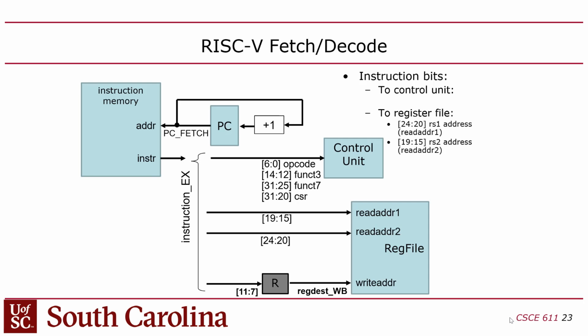We have control over the RAM. We know it's a 4K by 32. It's 32 bits wide. So if you increment it by 1, you advance 32 bits, right? So I just made it word addressed, again, just to keep it simple. But if you remember from 212, that was incremented by 4.